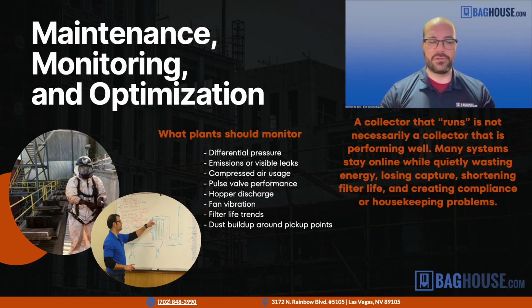So things like using the wrong filter media, undersizing the dust collection system, not designing the hoods or the source capture very well, or as we said, modifying it over time, adding more pickups, diverting things around, butchering, chopping up, and pasting back together the ductwork. Also, though, things like not having the dust collector settings correct. All of these kinds of things affect greatly performance elsewhere in the plant.